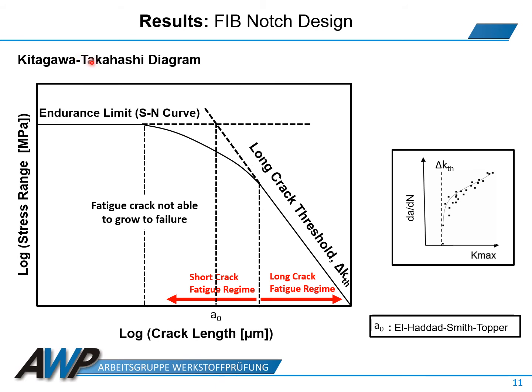I will make use of the Kitagawa diagram in order to explain the notch design. That is a significant step in our research work since we want to make sure that we are within the short crack regime. As mentioned before, that's where the local microstructure governs the fatigue behavior. The diagram initially combines the fatigue endurance limit and the fatigue long crack growth threshold as a single plot.